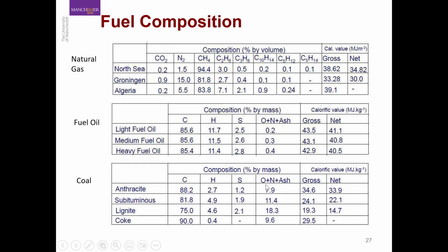But here you also have a lot of NOx and ash, so you are going to have a lot of particulates in the flue gas, and that is going to cause pollution as well. For liquid fuels and solid fuels, you have to treat your flue gas and take it to a scrubbing unit where you remove SOx, NOx and particulates before you can emit it into the atmosphere.